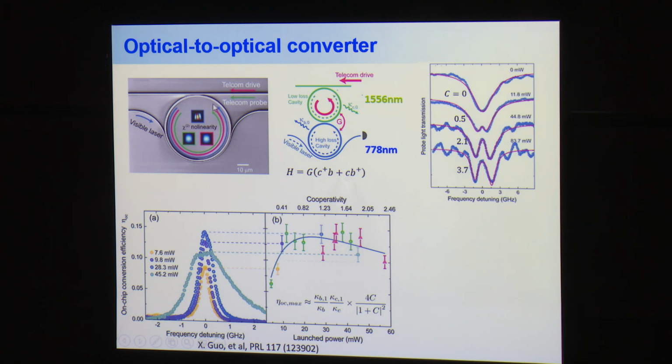And so in this device, we have a 14% total conversion efficiency, even though the internal conversion efficiency is 100%. The reason is that when we first designed this device, we wanted the signal in the harmonic mode to be critically coupled. This turned out to be not the best design, because if you look at this conversion efficiency, this is a pre-factor, the corresponding loading factor. If you are critically coupled, this is 50% here, and this mode is also 50%, you would expect only 25% total conversion efficiency. So if you want to drive this device to have 100% conversion efficiency, you would like to have both modes be overcoupled. This is very important to realize: you want the optical modes overcoupled to have high efficiency, so you are not lost by the coupling.